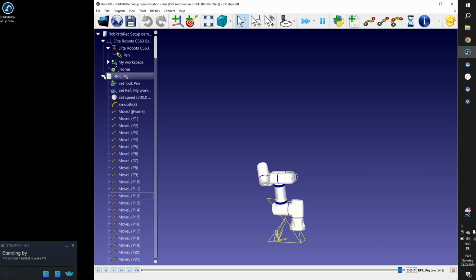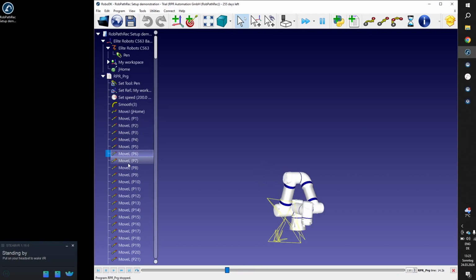And what we will do, I will move back to the robot. I will connect the PC with the robot, and we will test on some particular points if we should align any kind of offset. I'm talking right now especially about the Z. We can fine tune it in front of the robot, and if we think we are ready to go, then with some mouse clicks we can export and transfer the program to the robot, and we can start it from the teach pendant then. So please follow me and let's do the last steps.